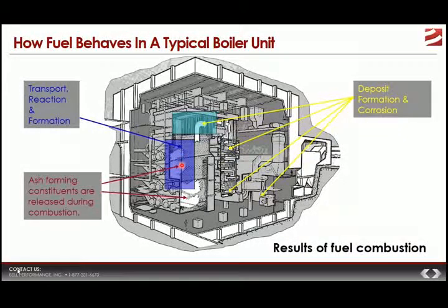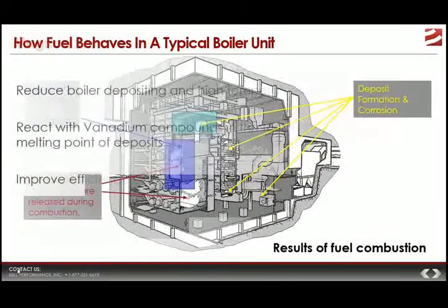You have different kinds of deposits being formed, some of which are pretty strongly associated with corrosion problems. So when we consider what we need to do to create the most problem-free HFO use experience, these are all areas that we need to look a little more closely at.